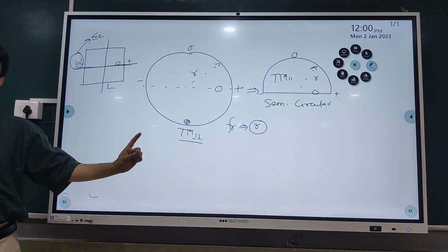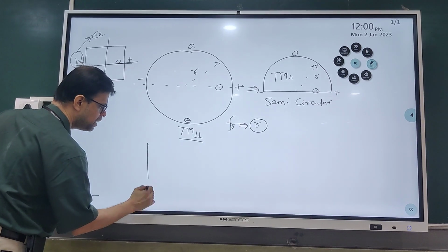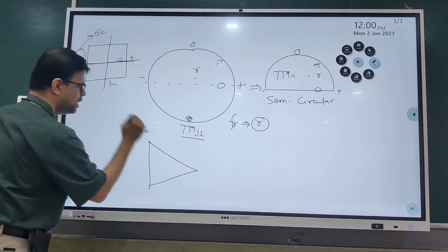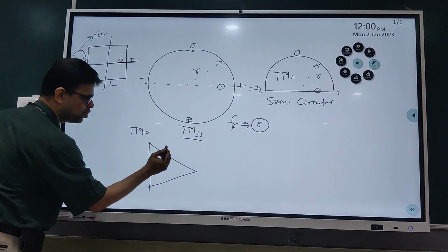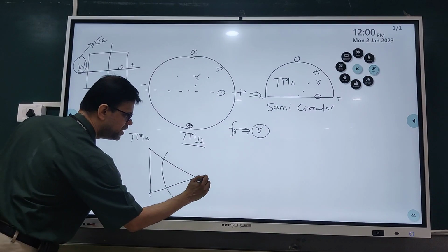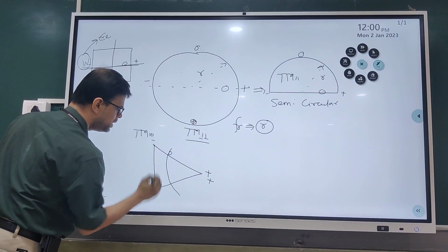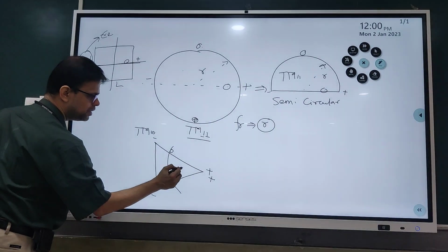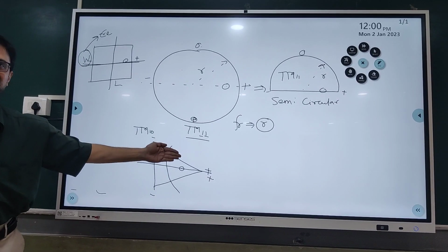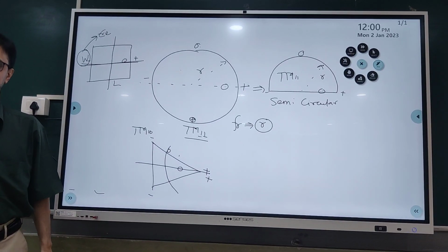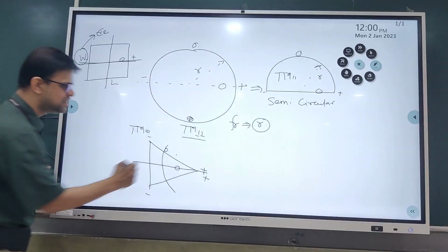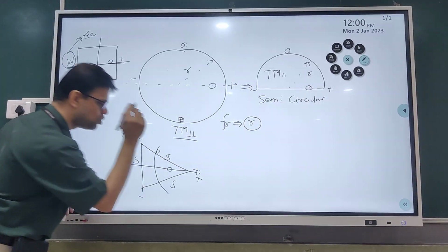Now, continuing with the same, this is your equilateral triangular microstrip antenna at fundamental TM10 mode. As we know, the fields are symmetrical with respect to the centroid line. So here the field is positive, 0 and negative. It is symmetrical. This is, of course, your coaxial feed location. So the fields are symmetrical in nature across the feed point axis. And the resonance frequency deciding dimension here is the side length S, which is present throughout.